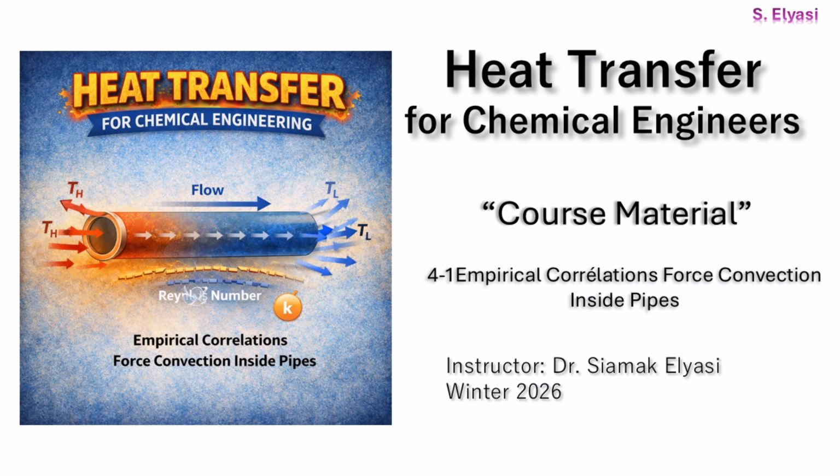Second, for a fully developed turbulent flow in a smooth tube, the go-to formula is the classic Dittus-Boelter equation. A key thing to remember here is that one of its exponents, n, actually changes. It's 0.4 when you're heating the fluid, but it's 0.3 when you're cooling it.